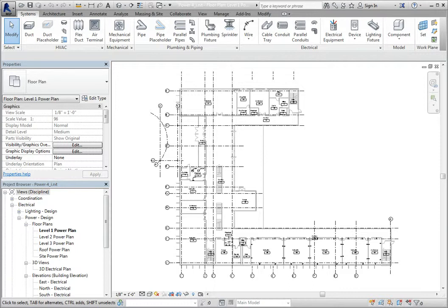Revit also creates a temporary wiring layout for each circuit created. You can use the temporary wiring to generate wiring for the circuits defined in your model. For example, in this project, the electrical fixtures in the south portion of the building have been assigned to circuits.